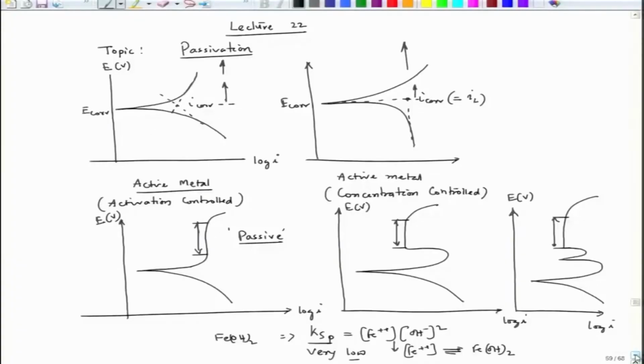Okay. So, now when you talk about passivation, we always refer to this kind of graph, and of course, this particular graph is a typical graph which confuses us as to whether the metal is attaining passivity or not. When we experience this graph, it has an origin. We will talk about that origin, why this graph appears. We call this segment unstable passivation, and these two are forming the stable passive state. This particular segment is spontaneously passivating.